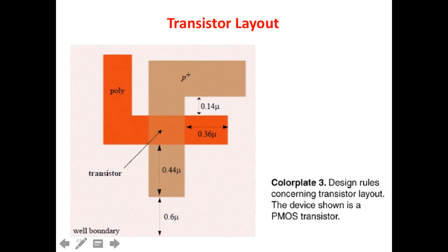And the reason for this is easy, because since you do not have a perfect alignment between the two layers, if for some reason the polysilicon stops here instead of here because of errors and tolerances of alignment, you have here a short circuit between the drain and the source, because there is a P plus region which is connecting the drain and the source.